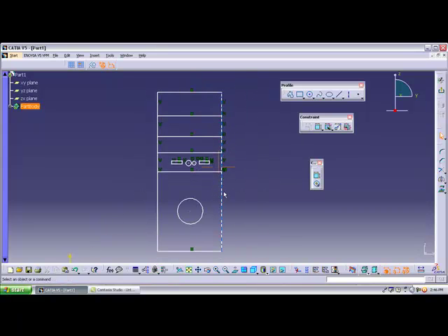It is not exactly in the length and dimensions of a CPU, because it is not in perfectly shaped dimension. So what should we do? After making the dimension, the geometric constraints are applied automatically, so we don't bother about them. If it doesn't get a geometric constraint, then we should apply it. So geometric constraints are automatically created. After that, we should apply the dimensional constraints.